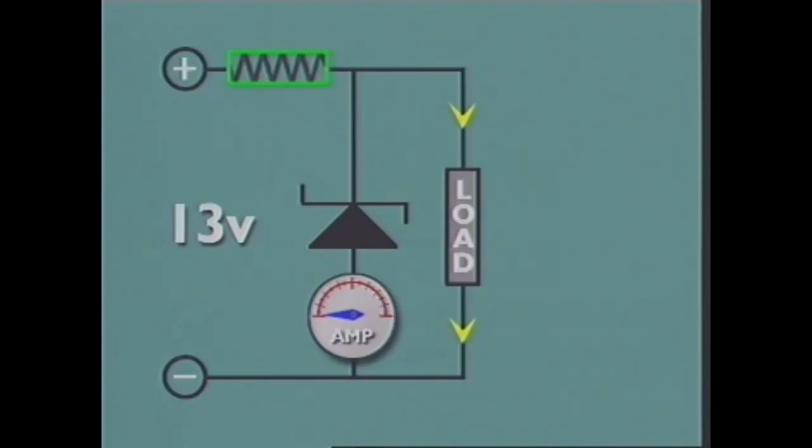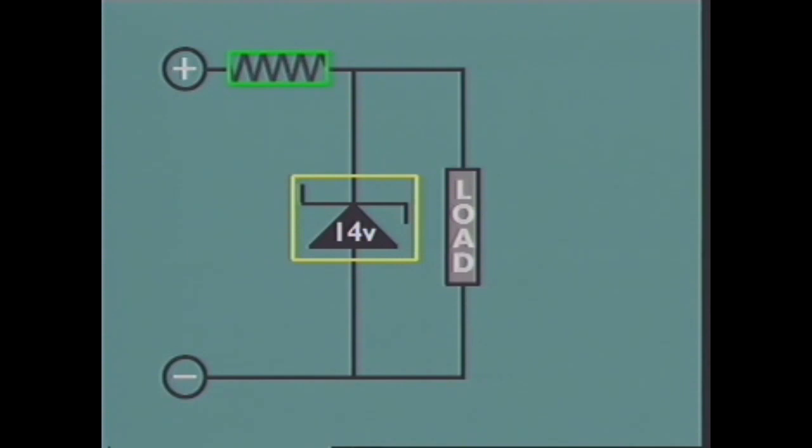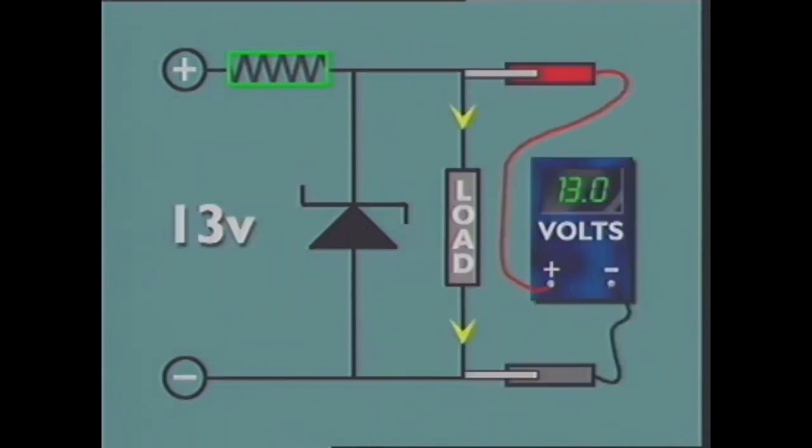It is blocking current flow through it. But if the voltage of the current source is large enough, it can force current to flow through the diode. This is called breakdown. A Zener diode is designed to operate in this way. As breakdown voltage is reached, the Zener diode's resistance suddenly collapses. It lets a large current flow through it without damage.